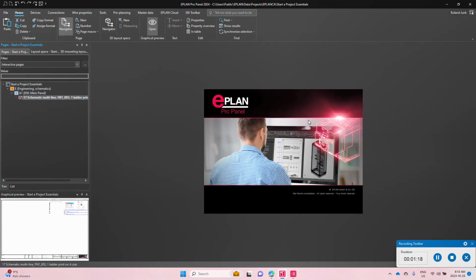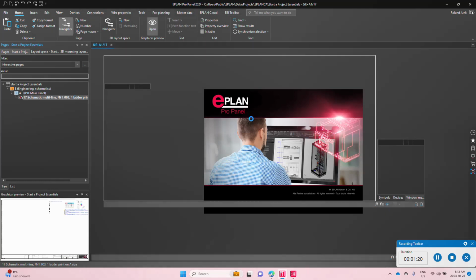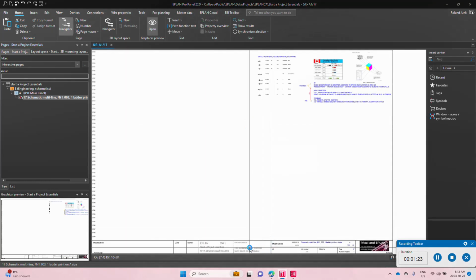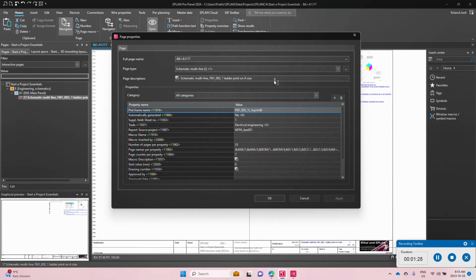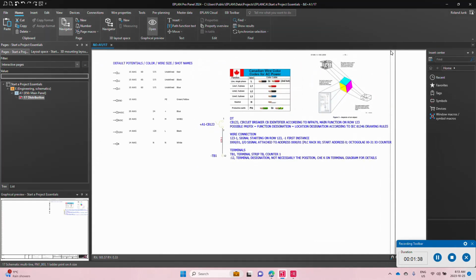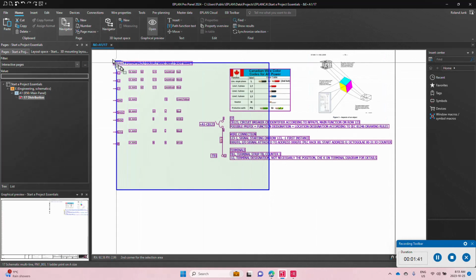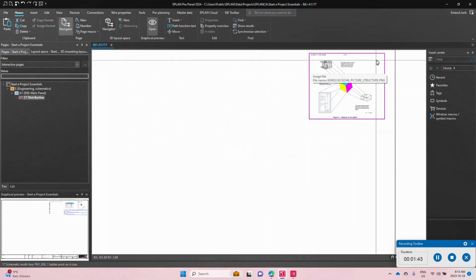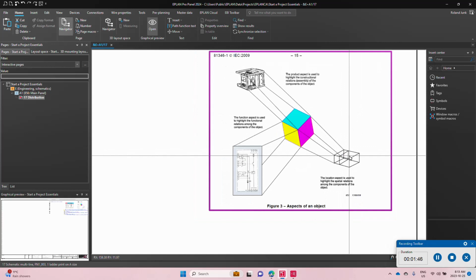So technically, when you look at a schematic page, all you really have to think about is, of course, your plot frame. Do you want one ladder, two ladders? Just describe what this is, distribution, and the page. Now the page you can see is a little bit more complex in my case, because why? I have decided here to actually use a concept. My wire colors are of course here by the Canadian code, but let's talk about the devices here. I'm using the device concept of IC to identify the location of my device as well as what it is.